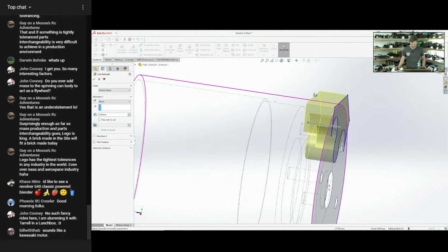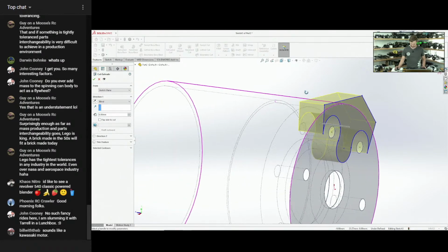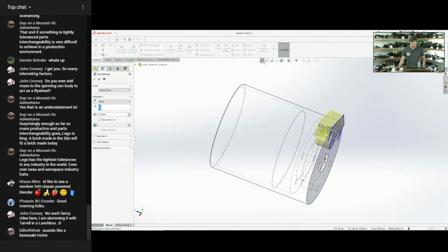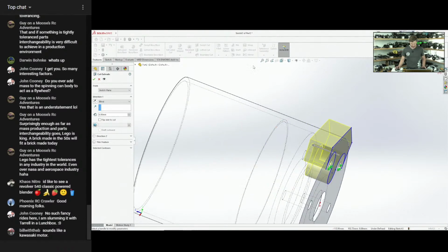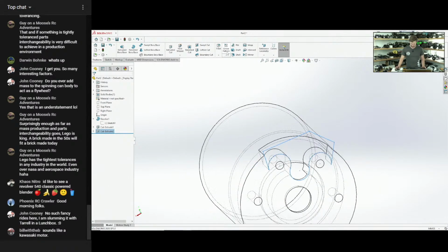It won't be too thin. Again, this is where experience comes into play, knowing how thin is too thin on a face. All the years that I machined our puller housings in-house, I really got a feel for what is too thick and what is too thin. And of course, it depends on the materials as well. But there we go. So we have one cut on this guy.